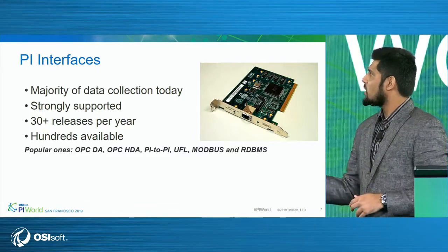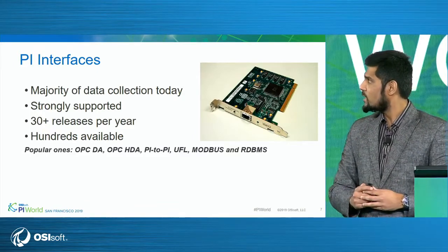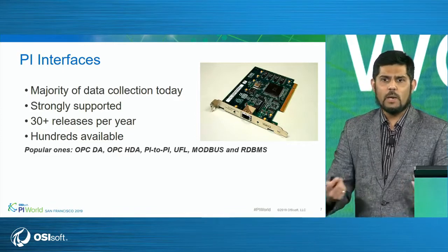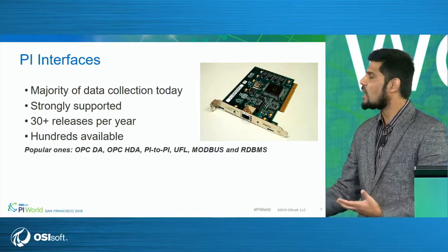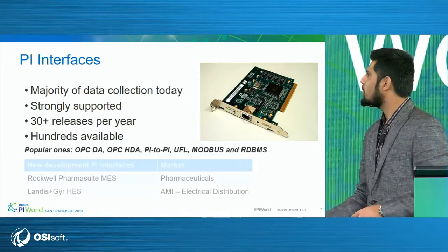Last but not the least, we have the Modbus suite of interfaces that allow you to collect data from a number of devices, be it daisy chained using RS-485 cables, or be it devices that are connected to your local Ethernet.